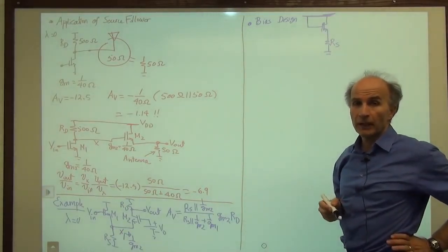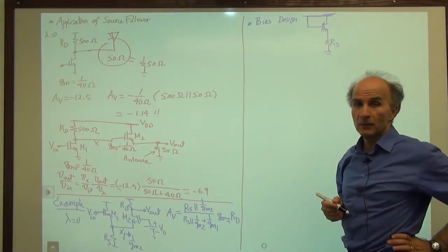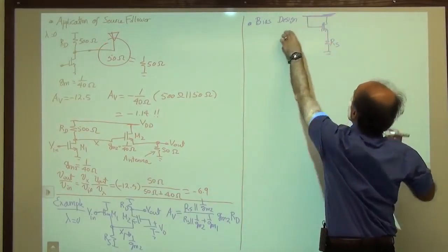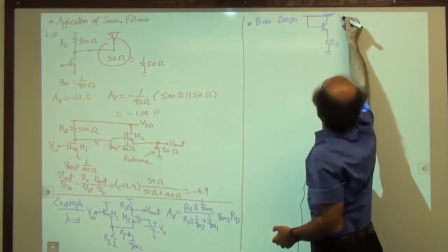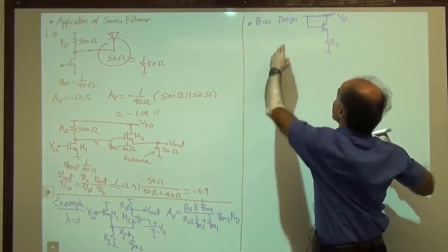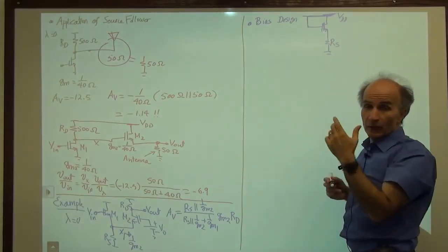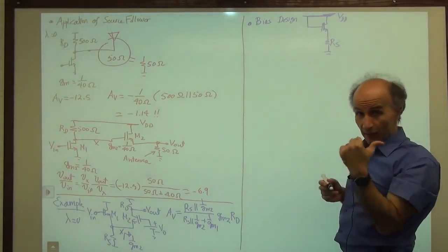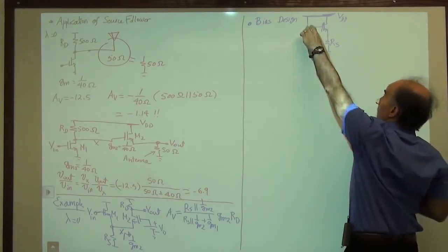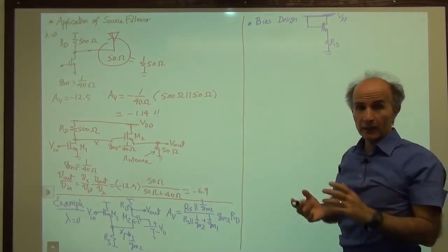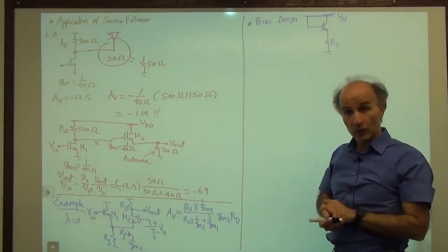Is the transistor biased properly in this case? Looks like it. We see that the gate is at VDD, so some voltage, 1.5 volts, 2 volts or something. Then we have some VGS, then we have a resistor here. So this is actually similar to the common gate stage we analyzed last time. So we have some VGS here, some drop here, we can have some current, we can calculate and we can get what we want. So that seems doable.